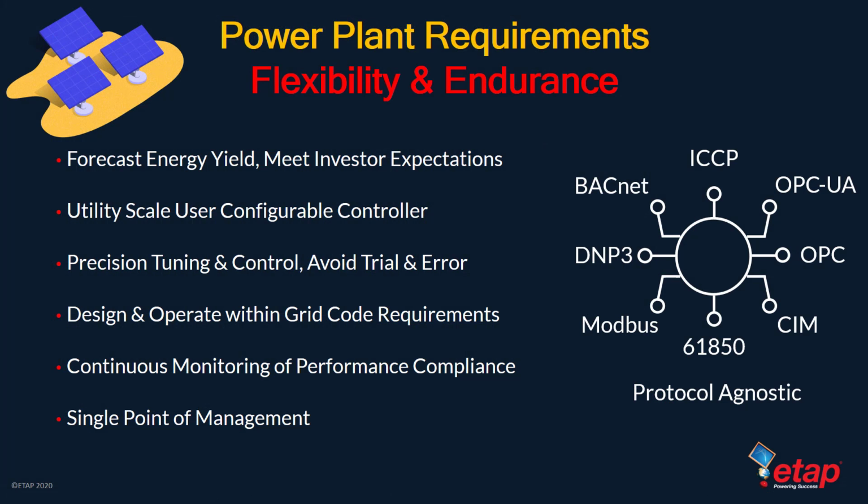Utility scale users require a configurable controller. This is because the goal is to maximize power output and therefore revenue while supporting a stable and reliable grid using this configurable capability. However, the logic used for the power plant controller must be capable of precision tuning and control, not only during design but also the operations phases. So let's understand this in a little bit more detail. It is possible that assumptions during the design stage may lead to a slow or fast responding controller that may need to be adjusted or tuned during the commissioning phase.